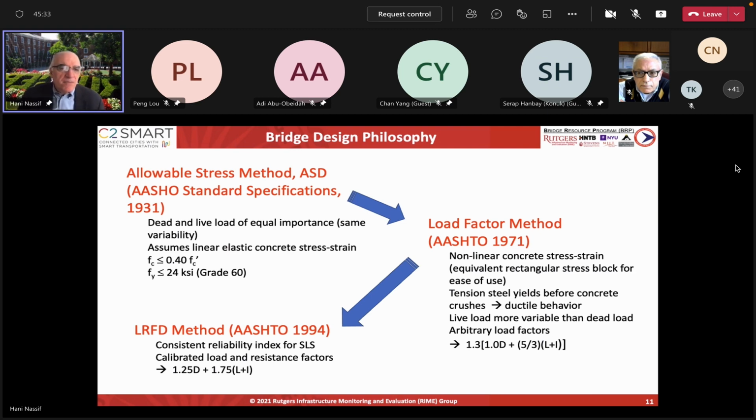And we basically put two allowable stresses. One is about 0.67 Fy. Fy at the time was about 36 ksi. And for the concrete, up to the point of cracking in compression, and even less than that. So those were the main things that came about in 1931.